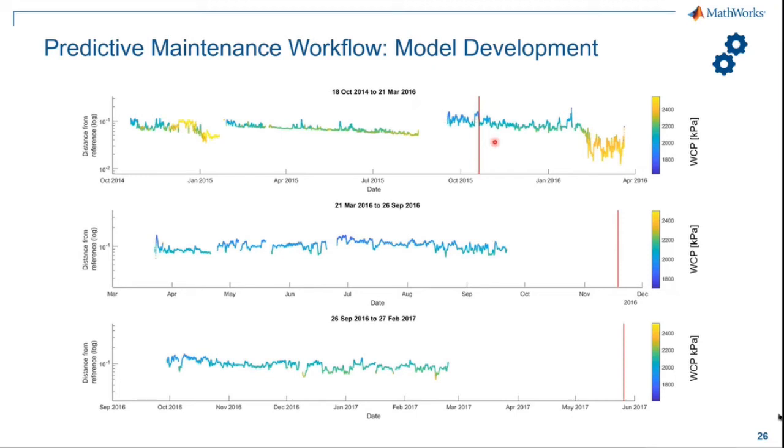But from the gap in the data, which is about a month long, we know that the turbine was actually overhauled, which explains why it appears to have been washed too early. We also see that shortly after the overhauling, the efficiency of the turbine dropped quite rapidly. And in this instance, Peter and the team knew it was due to the poor steam quality at that time.